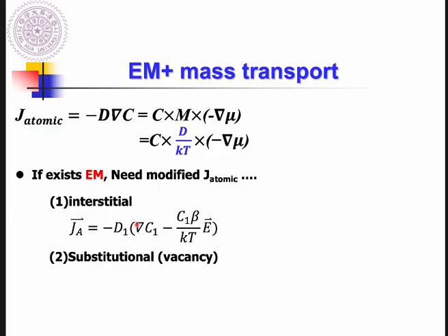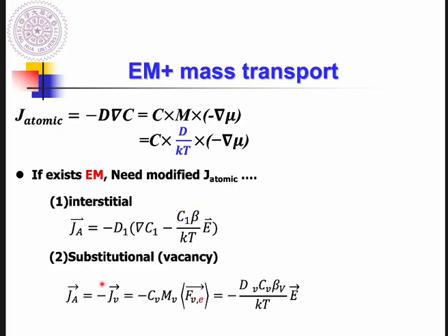So we have the mobility, concentration, and also the driving force beta E. Okay, and for the case in pure metals, we only have the atoms and vacancies in this type of system. In order to know the atomic flux, it's quite difficult to measure it directly, but we can analyze the vacancy flux by visualizing the volume of the voids formed inside these materials.